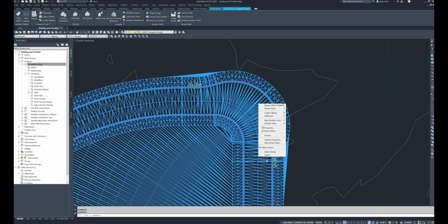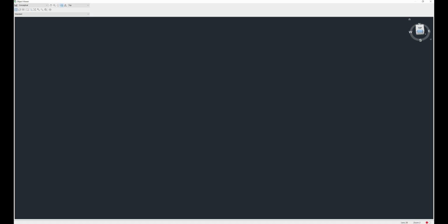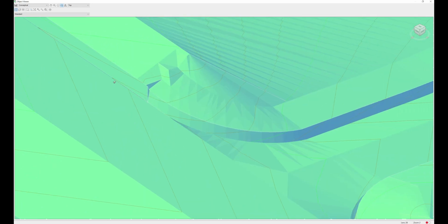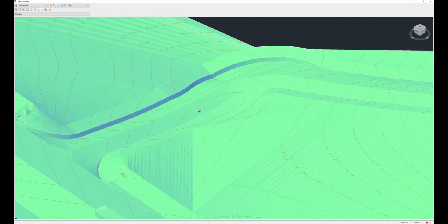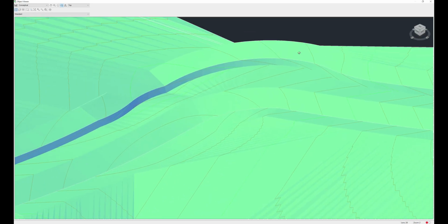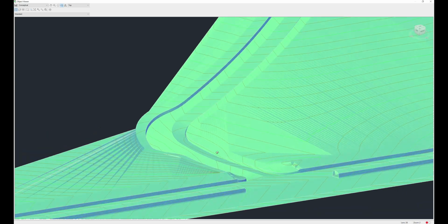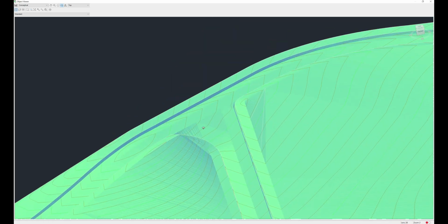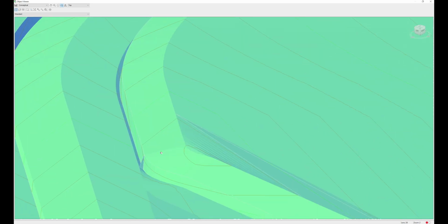So I am going to, again, view this in 3D, and we're going to take a look at those intersections, and we're going to take a look at the majority of our surface and make sure it's a nice, smooth surface around the corners. There will be a few places like this where we have, like I said before, a rolled face joining to a straight face curb. We'll try and fix up our sidewalk connections. This is also exaggerated 10 times, so we do see the little bits of the triangles here. Rotate it around and take a look at it. Make sure everything is nicely connected. And I might turn off exaggeration, and we'll Object Viewer this again. We fixed some triangles in here. It looks like there's probably one more that we need to go take a look at.